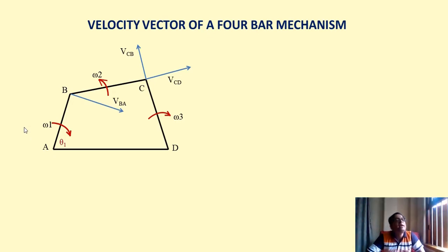When the situation arises that the angle ABC is greater than 90 degrees but less than 180 degrees, then always remember, due to the inertia force acting individually on these particular links, whatever may be the direction of rotation of AB, which is called the crank, the connecting rod BC will rotate in exactly the opposite direction.